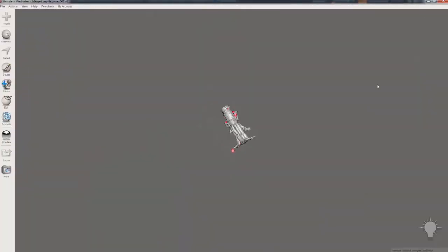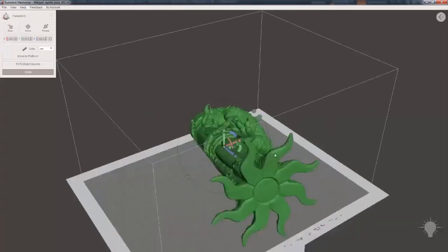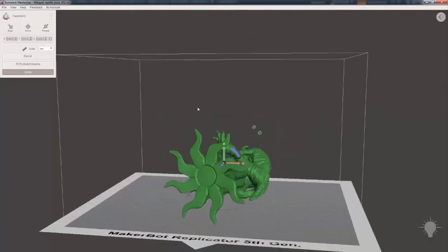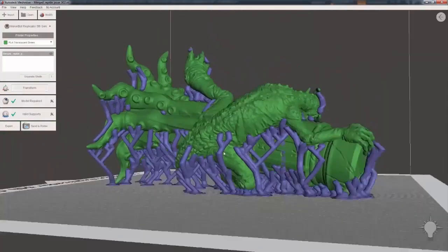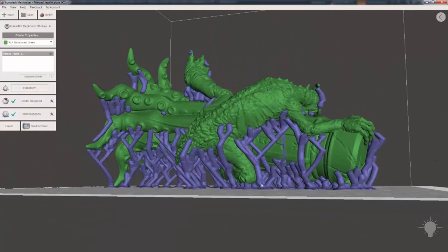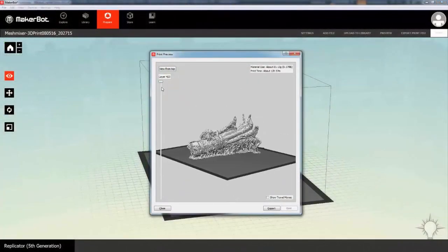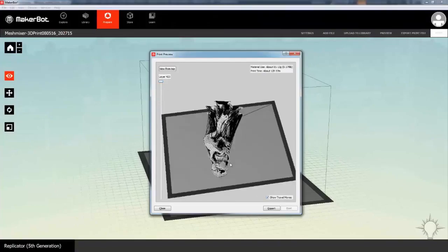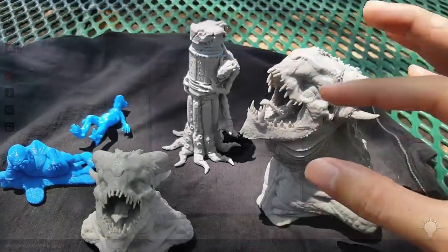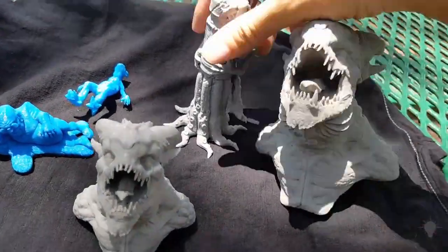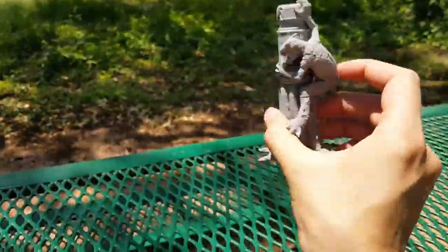Finally, Louise Krull is going to go over the 3D printing process for this object, from exporting the mesh out of ZBrush, using Autodesk's free program Mesh Mixer to clean up and add proper supports for the printing process, and finally go into MakerBot's free software to allow you not only to preview the print, but also find out how long it'll take to print depending on the settings you choose, and even how much filament you're going to end up using. From here, you can send it to your own printer, or export everything to a file to hand off to someone else to use with their printer, with all the files, support, settings, and options that you want.